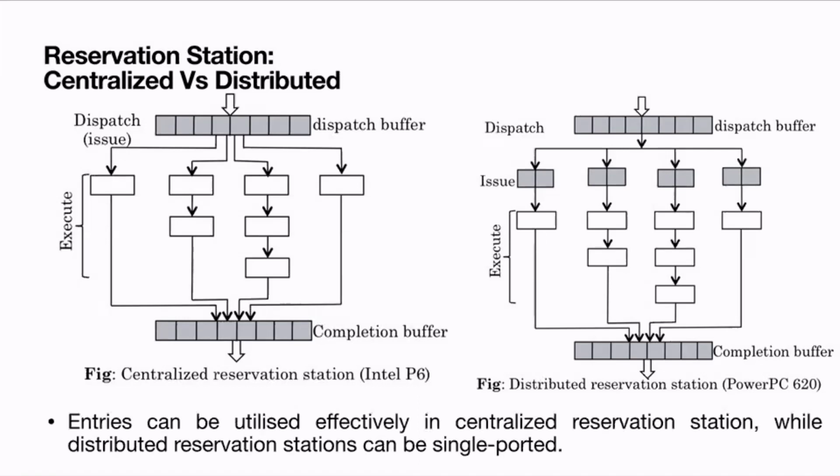Right. So this is a reorder buffer. As I said, in the architecture of a superscalar processor, some pipeline stages are in order, execution is out of order, and the complete and the retire are again in order. So to handle this, we have a reorder buffer.